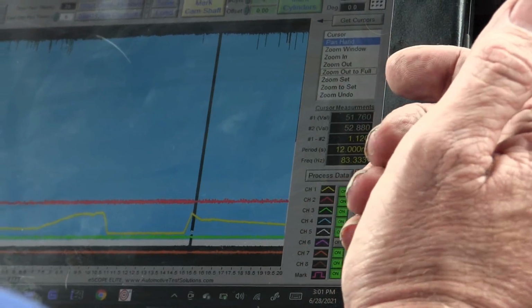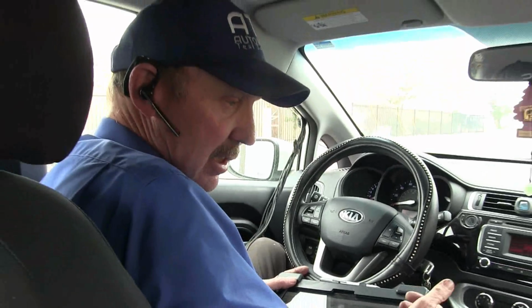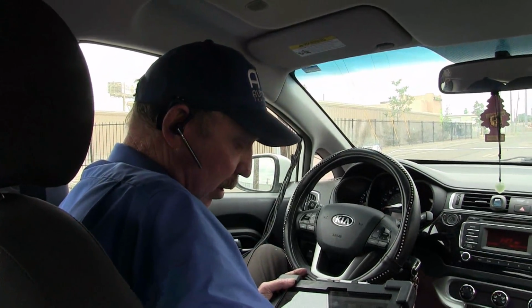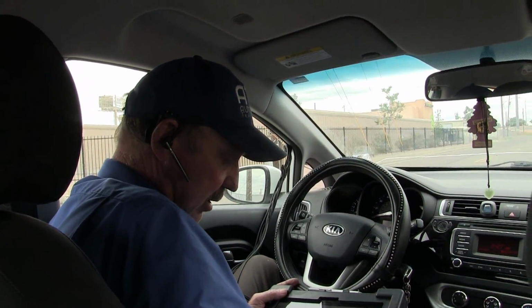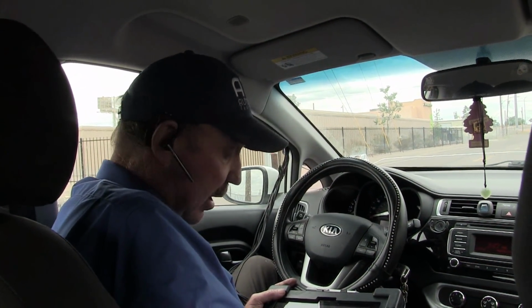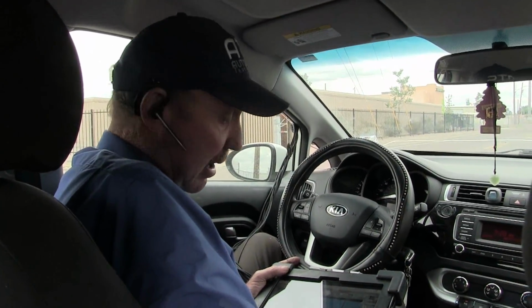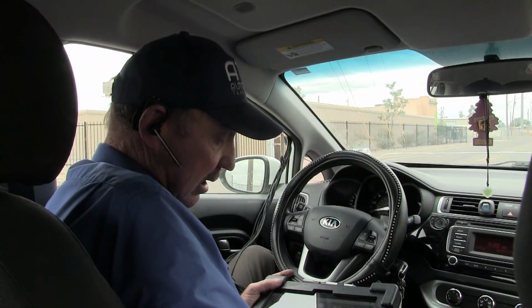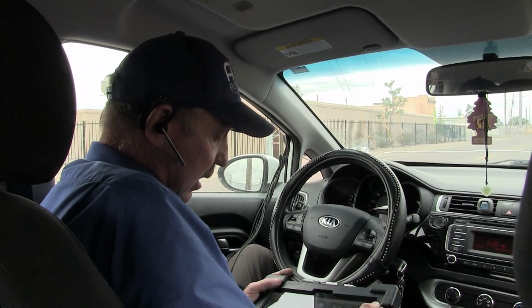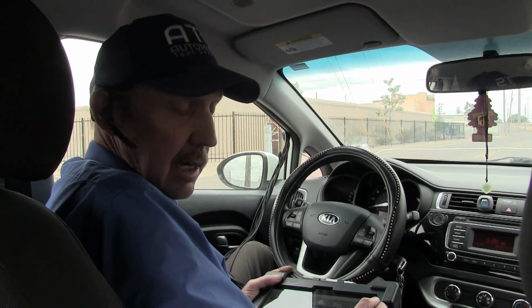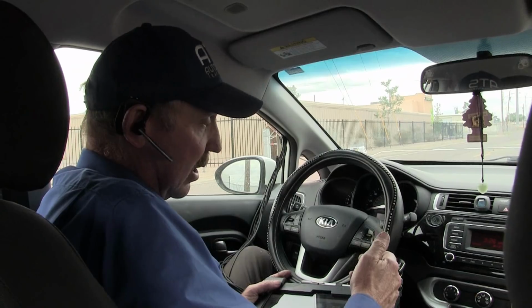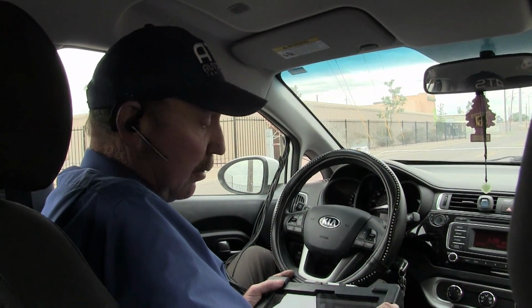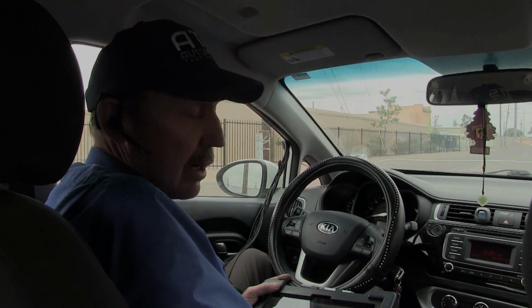And if the primary system, if the lift pump can't supply the high pressure pump, we would lose pressure just like this. So I know they've done a lot of work on this car, but I think the problem is somehow in the pressure feed. So I want to go get set up to check the fuel pressure on the low side and an amp clamp, and we'll try to figure out what's going on with this car.